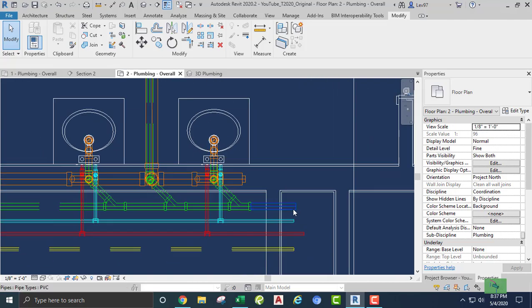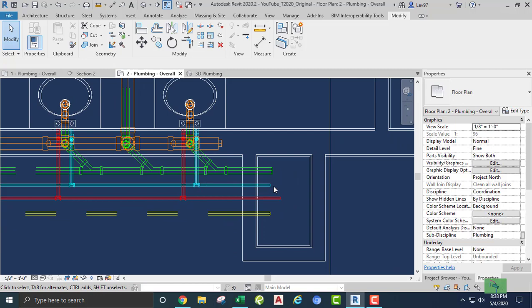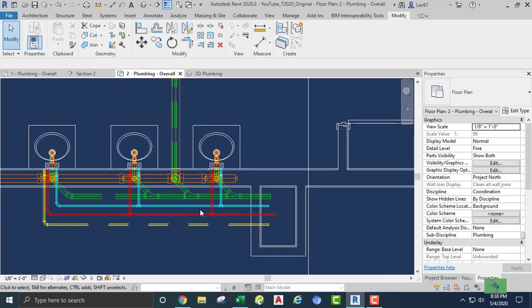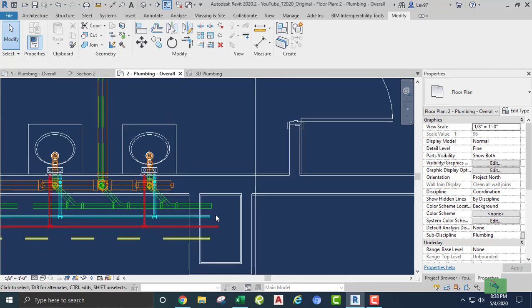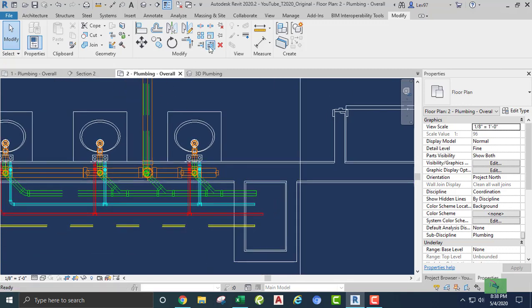Okay, the vent will have a riser that goes to the roof, and the second level water pipes will have an elbow, right? Going to each, from the first floor, going to each fixture on the second level. Okay. What am I doing? Okay, let's trim these guys back. Trim. Multiple. 1, 2, 3, 4. Okay, on the second. Well, yeah, that's fine. Okay, so going back to the first level.